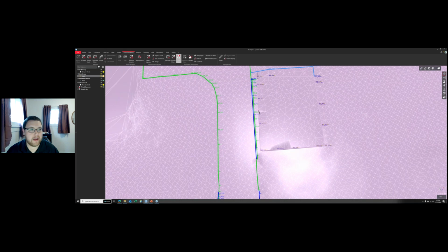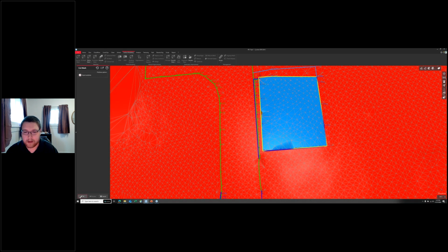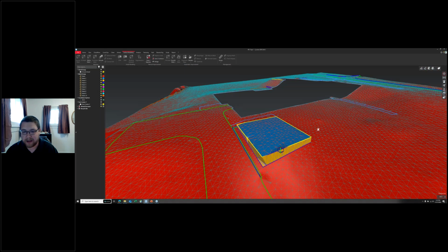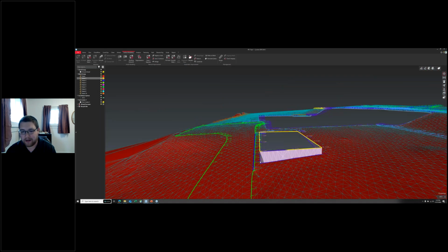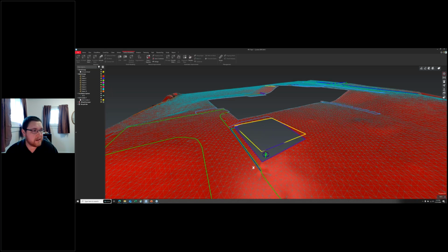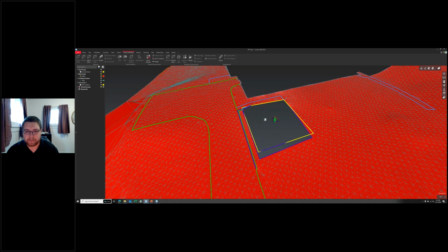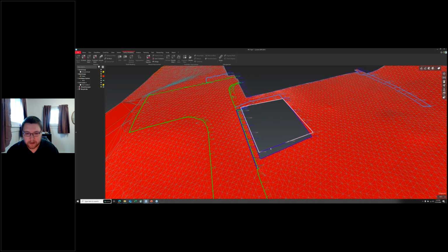And I'm going to do that cut mesh. Make sure you have project poly lines on, so it's going to hold those lines all the way and put them out for you. Now I have a couple different meshes. I have a top mesh here that I could delete out, and then there's this mesh on the sides. Really, the only mesh I need to keep is the red one, so I'm just going to remove all these. Now I've cleaned up all those points, and what I'm going to do, we talked about the sharp edges tool.